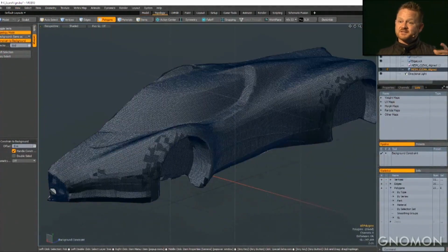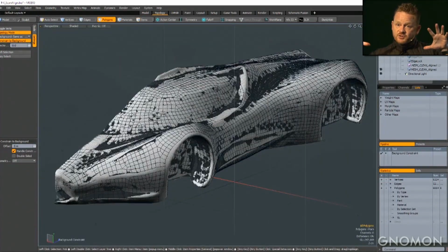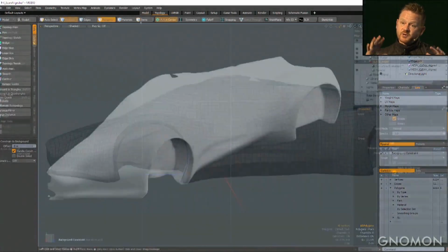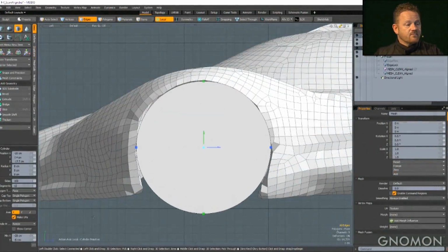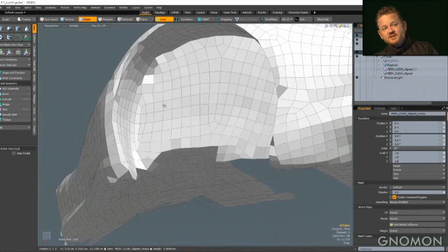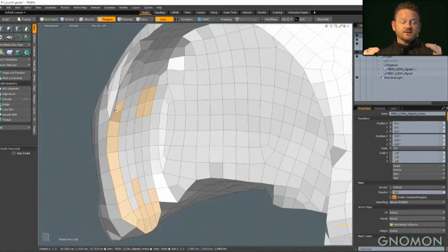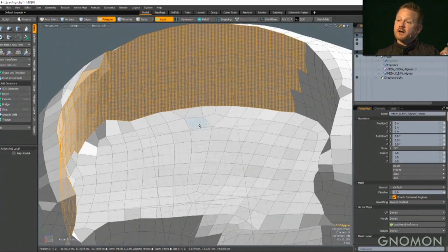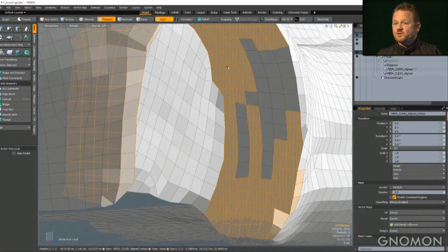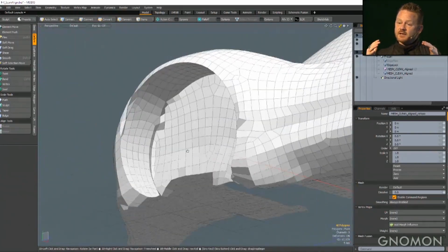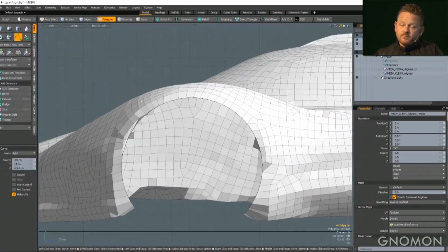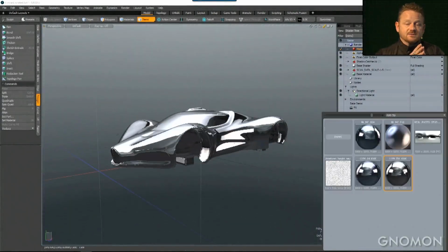And I've shown designers how to take that auto-retopoed mesh and shrink it back over the original clay, so you can kind of shrink it back down to guide and give it some correction if you see any kind of misalignment. And then also to use the push tool up against a predetermined size cylinder to help correct some of that. So I'm just using my pen tool, most designers can use a Wacom tablet, as mentioned, and just push that into that diameter wheel. And by doing that and using the already strong topology tools that are inside of Modo, you've got quite a skill set.